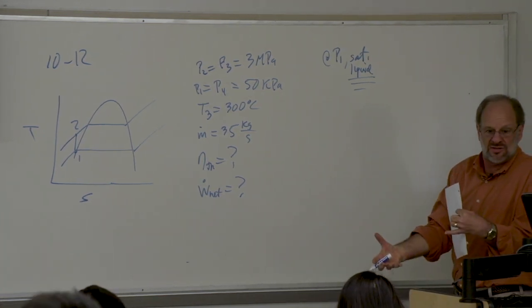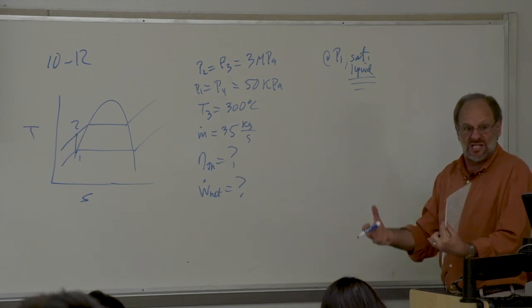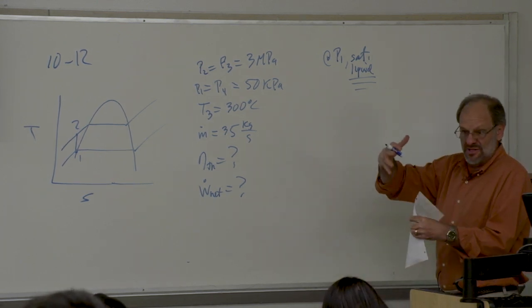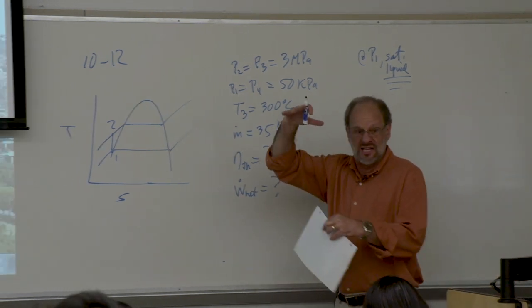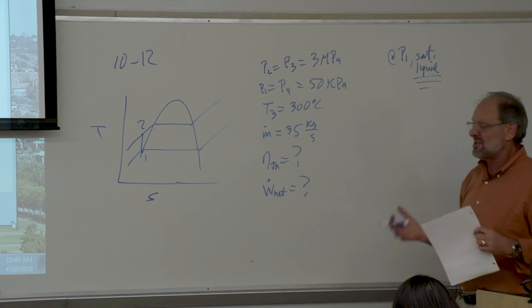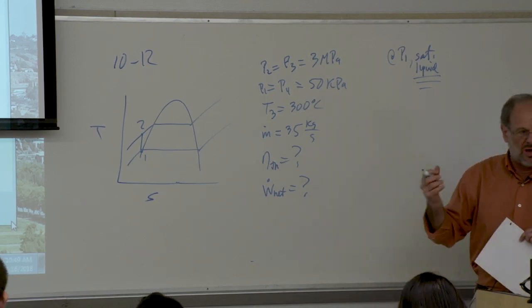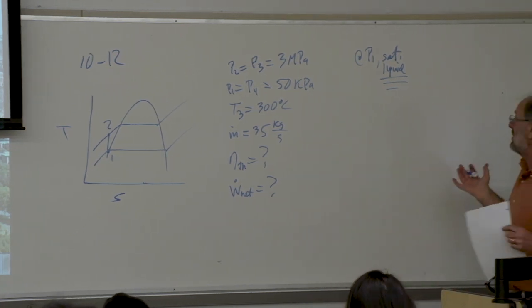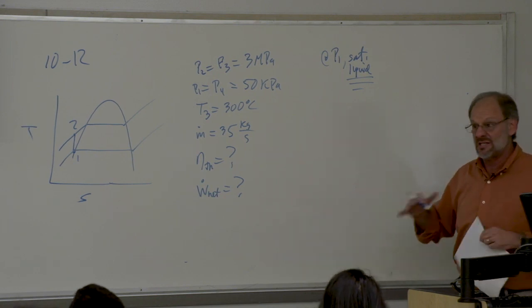It really just has to do with the design of the condenser. The bottom of the condenser is where the liquid resides, right? It's got a higher density. The steam, the vapor in the condenser, resides in the top portion of the condenser. So you just draw the water off the bottom of the condenser. It's a two-phase mixture in that condenser, but you're only pulling off the saturated liquid portion. So it has to be a saturated liquid. I mean, it is. It always is.